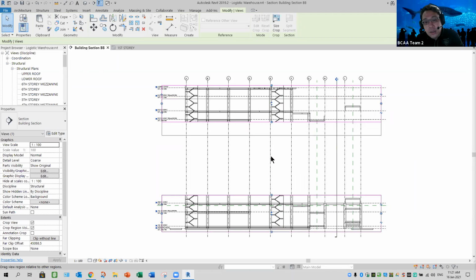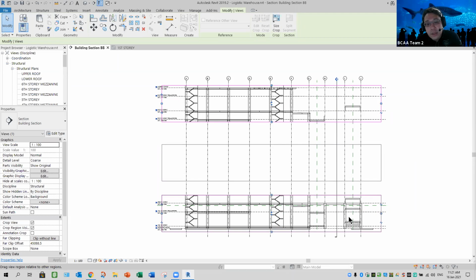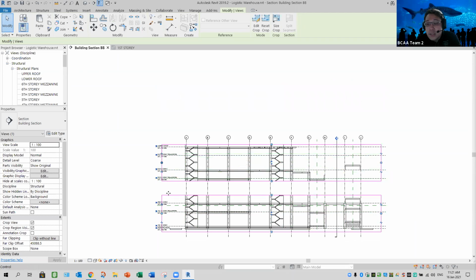By adjusting this, you are lowering it not physically, only graphically. The location and coordinates are still intact. When you compress or move them closer, my scale factor can be decreased. Maybe instead of 1 to 500, now it's 1 to 400.